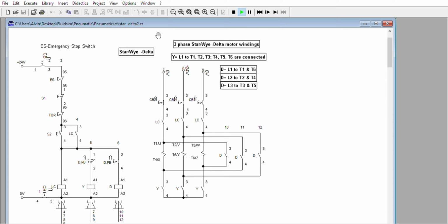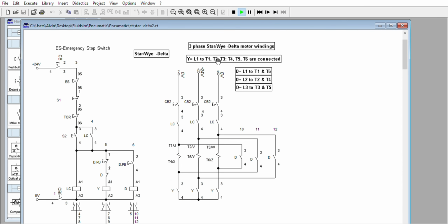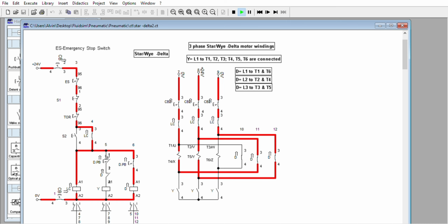First, this one. We need an interlock, of course, here from the delta contactor. Interlock break contact is to break a circuit or to open a circuit. So this will be D. Turn on, turn on. When this returns, of course, it will go back to star because we are using the detent switch, not spring return. So we will also solve that one. Turn off.